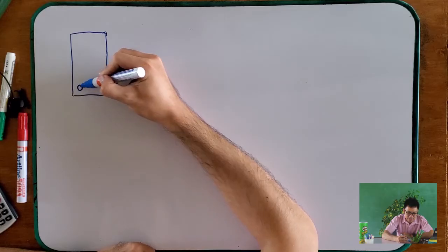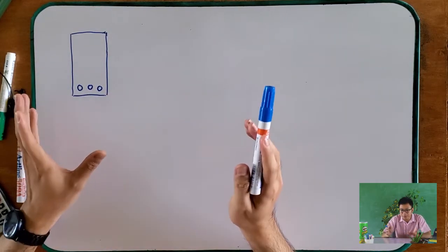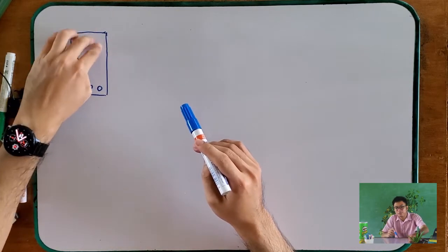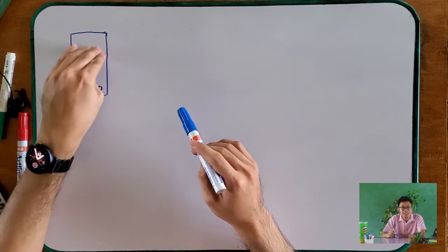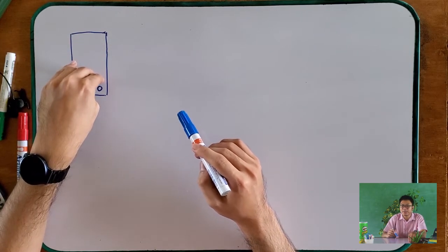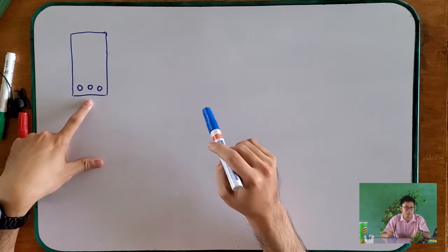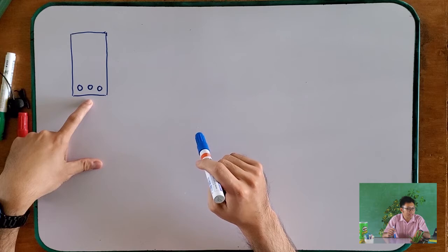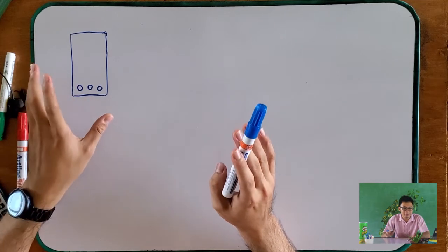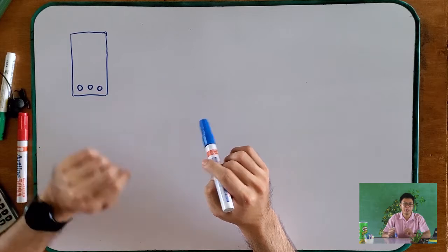And usually these reinforcing steel bars are placed below, not on top, because on top it is compression that is supported. So concrete is very good at that. But down here below our neutral axis there is tension, so our rebar supports the tensile load. Okay? So that is why it is important. That is how important your rebars are.